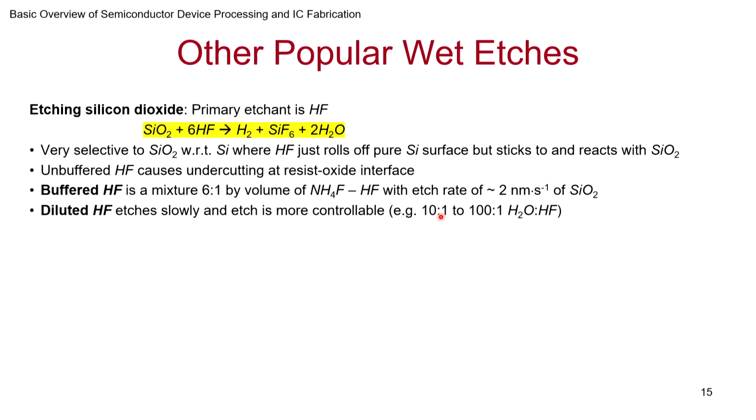Okay. So how do you know whether a wafer has a silicon dioxide native film or not? You can put a drop of HF. If it spreads out, there is native film sitting there. If it rolls off because it is just silicon, then likely there is no oxide. Okay. Of course, water also behaves that way. You don't need HF. Even water is hydrophobic to silicon, hydrophilic to silicon dioxide. Okay. But this etch is a very useful idea, and you might want to remember how etching happens.